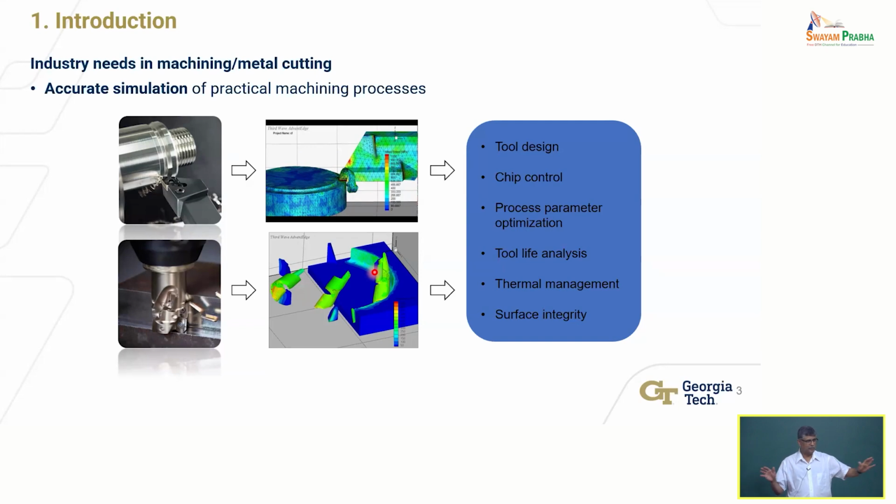If you think of wings of airplanes made out of aluminum, structural members, they are machined from a block, and 95 to 97% is machined away. So you generate lots of chips. Now, those are expensive materials, right? If it's a high-strength aluminum or it's titanium, then you can't just dispose of them.